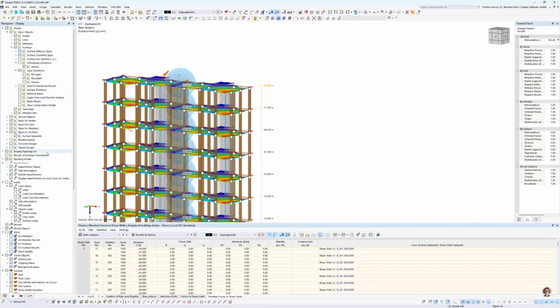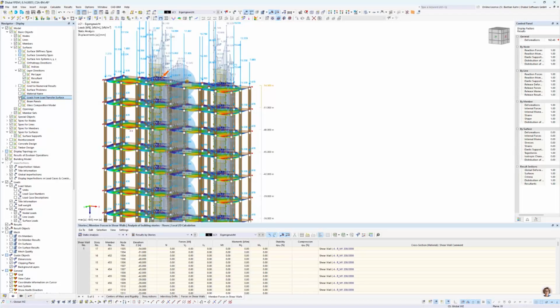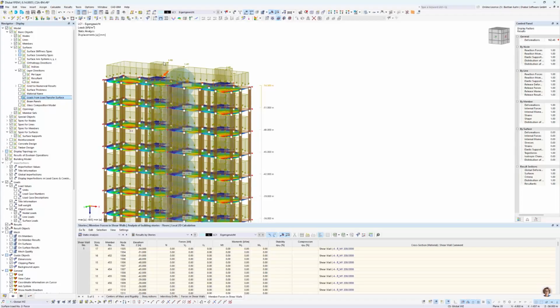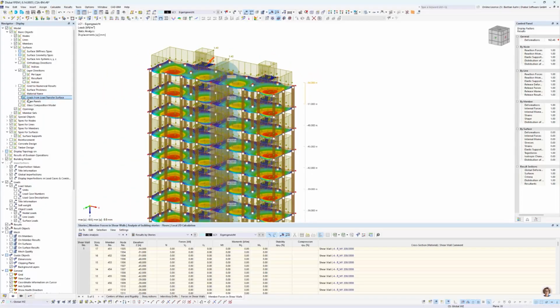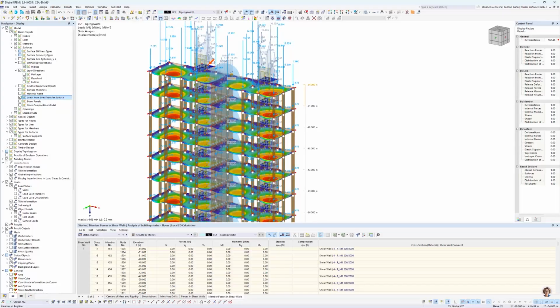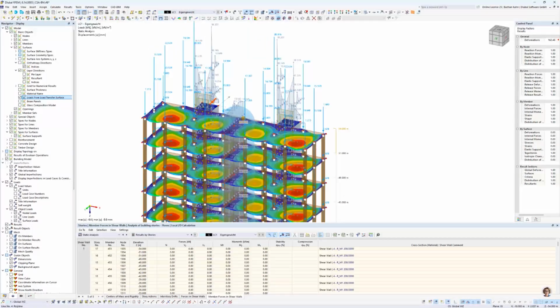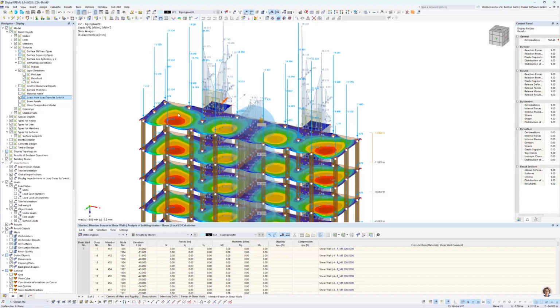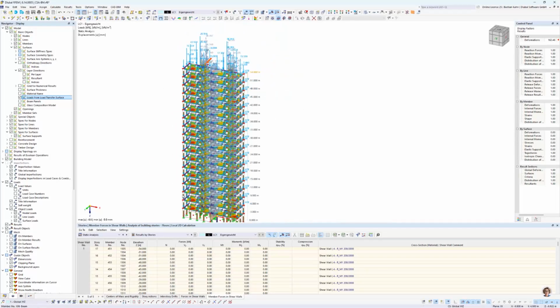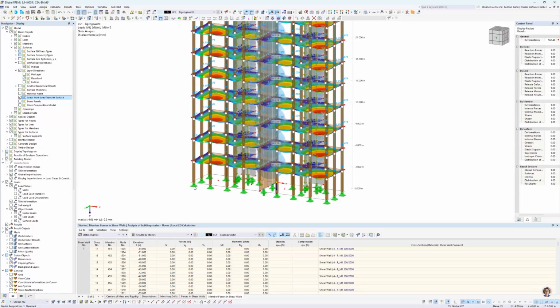And maybe we go to loads from transfer surface and show that again. So then go like this. And you see there's a force of 3.4 kilonewton per square meter on it. And we define loads from transfer load surface. You see that the load from the first story is summarized here and transferred to the other. Right? And this will then also regard the settling that I just defined via this option that we had.